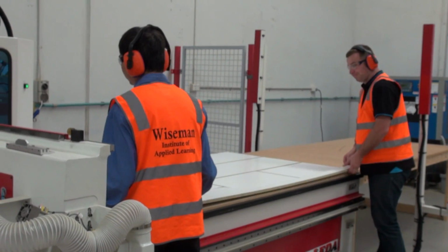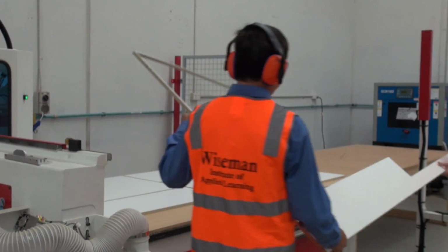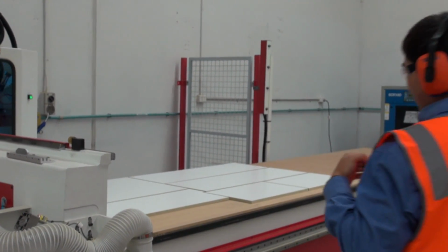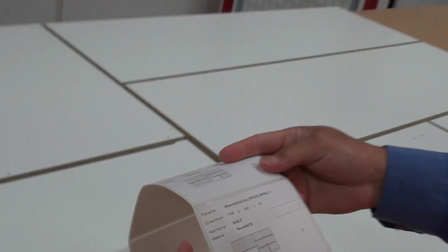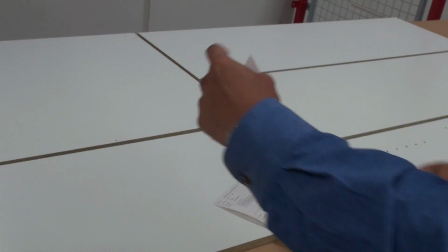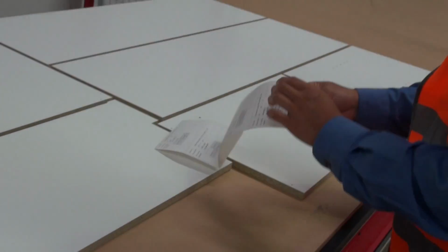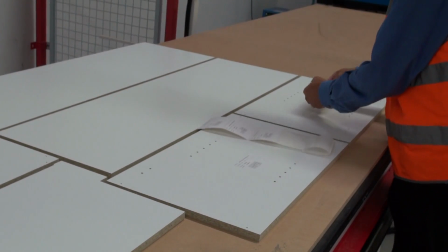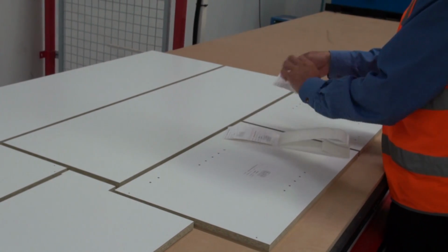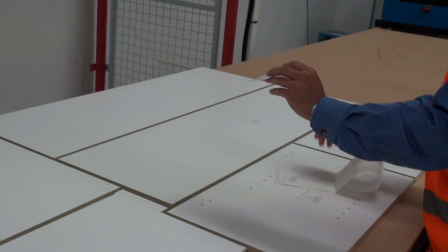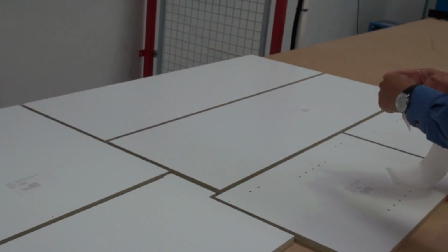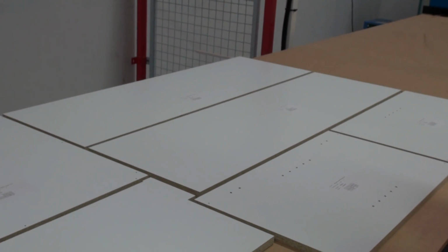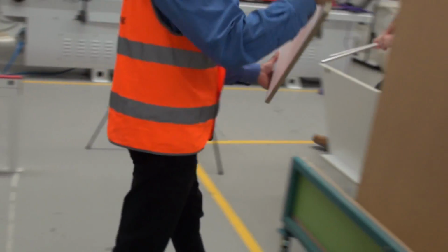Then you must remove and dispose of any offcuts. At all times follow the appropriate disposal procedure. Now place labels on each cut panel. This will guide you on how to assemble as well as which sides need to be edged by the edge bender. The finished panels are then stored in a single location so they can be identified.